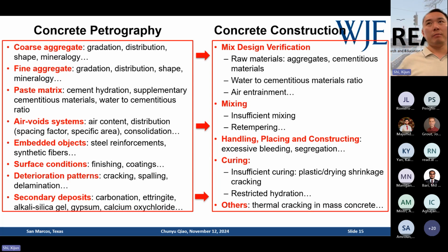And curing, that's a major aspect, especially for hot weather concreting or cold weather concreting. So do you have proper curing or insufficient curing? Do you have any plastic or drying shrinkage cracking, or do you have any early thermal cracking or not? And also, because of insufficient curing, do you have any restricted hydration, and so on and so forth?